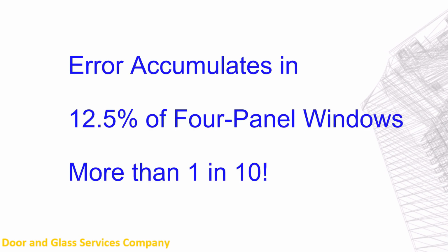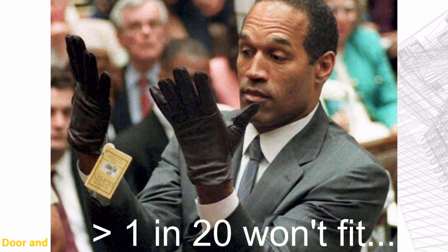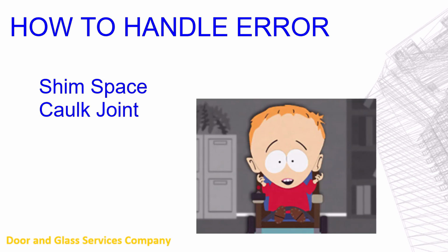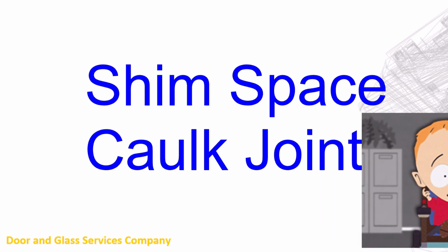Disregarding the measurement of the opening size, errors in 4-panel frames accumulate 12.5% of the time. If only 1/4 inch is allowed for shimming, as many as 6.25% of 4-panel frames may need to be modified to fit their openings when all the panels are fabricated within acceptable tolerances. Shim spaces and caulk joints are an important means for accommodating dimensional errors in measurements in manufactured products. Properly allowing for shim spaces and caulk joints reduces the likelihood of modifying product sizes in the field.